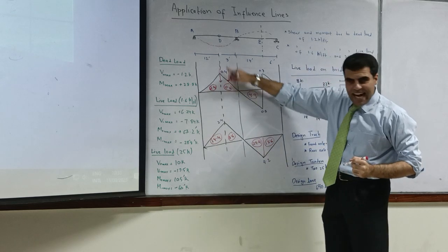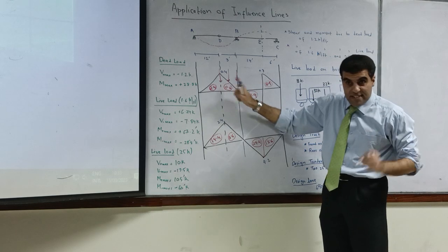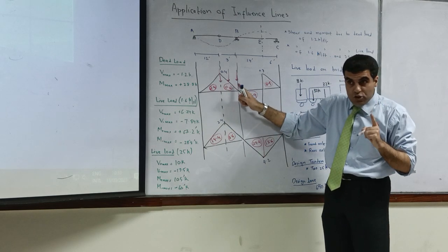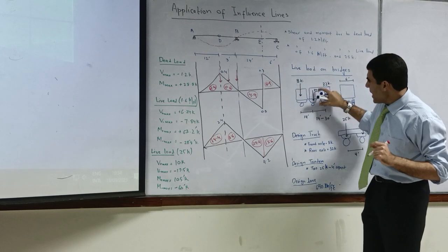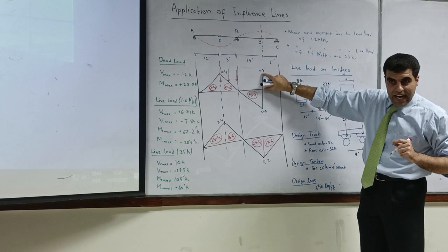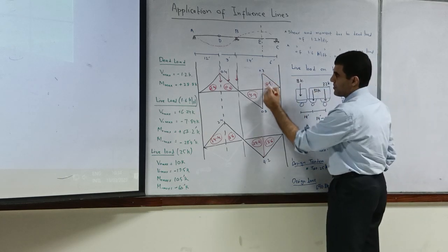And you multiply that with the corresponding ordinate. This is not area, it is a concentrated load, so with the corresponding ordinate. And similarly, you will place it over here, and you will multiply it with the corresponding ordinates.